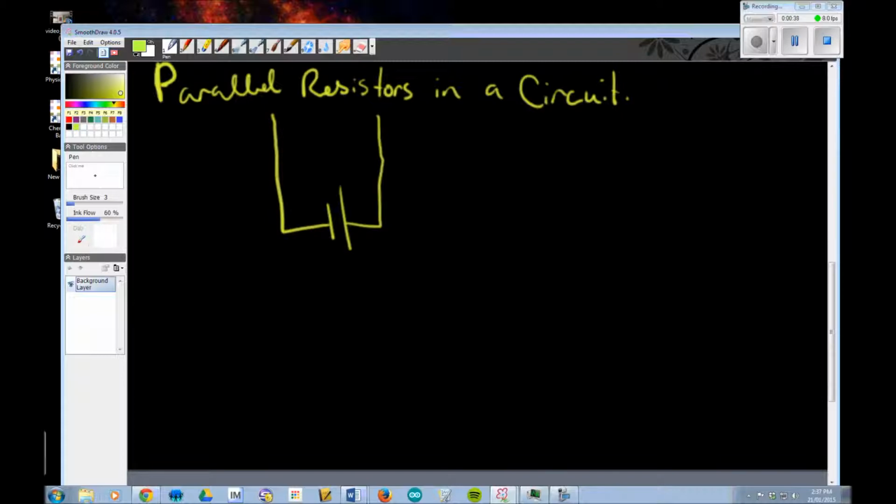And the first way to think about it is as if this is a parallel plate system, all right? And therefore we have, if you want, an electric pressure, electrostatic pressure, which attempts to push current from the positive plate to the negative plate. So if we put a resistor in the path of that current that's being pushed that way, and if that happens to be a light bulb, we'll see that it starts to allow current to pass, and the light bulb glows, and we understand that energy is being used as it travels from the high voltage to the low voltage.